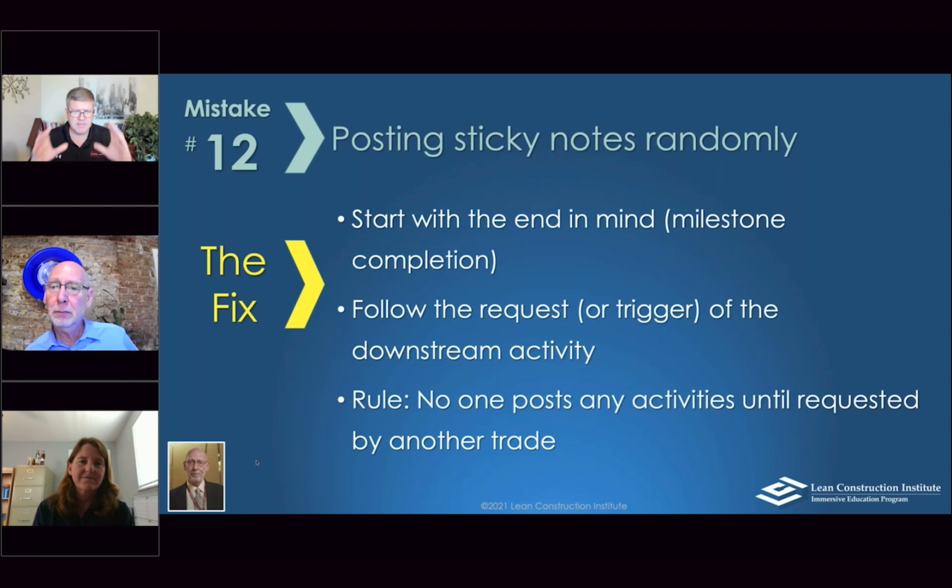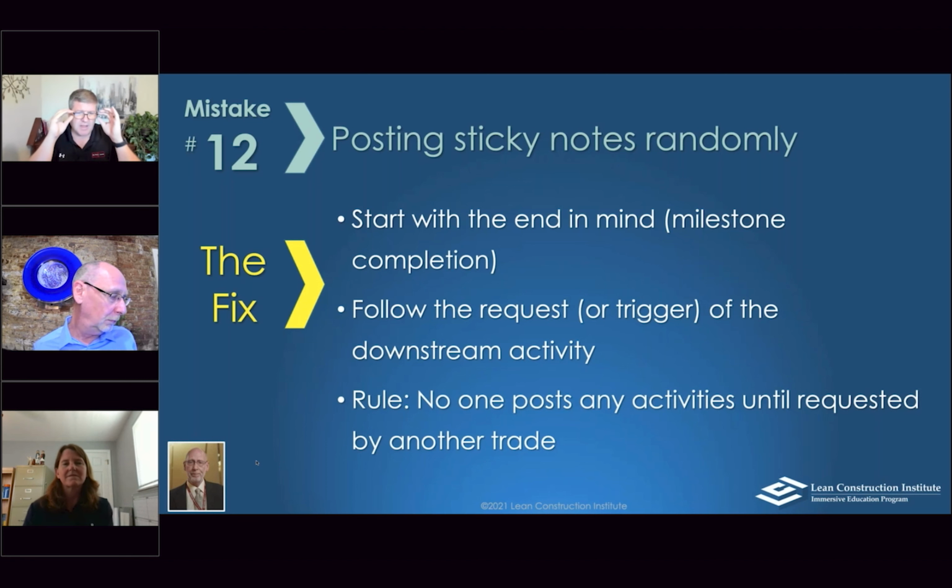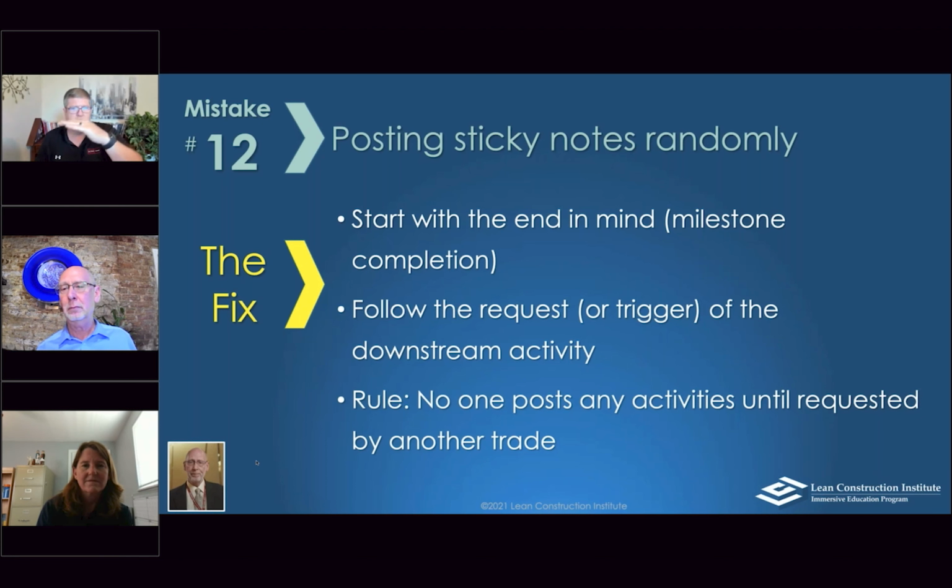Oh, good question. I like to have a more free-flowing layout based on the main handoff. I like to find out what's really driving the bus, who has the critical activities, and make sure that's first. I'll use a quick example to illustrate how I do the stickies. This is just forward thinking. If the concrete is the driver in the beginning, creating the foundations, then for a couple of weeks they're the most critical. They continue their foundation work, but then we need to start structural steel, so structural steel then kind of dominates.